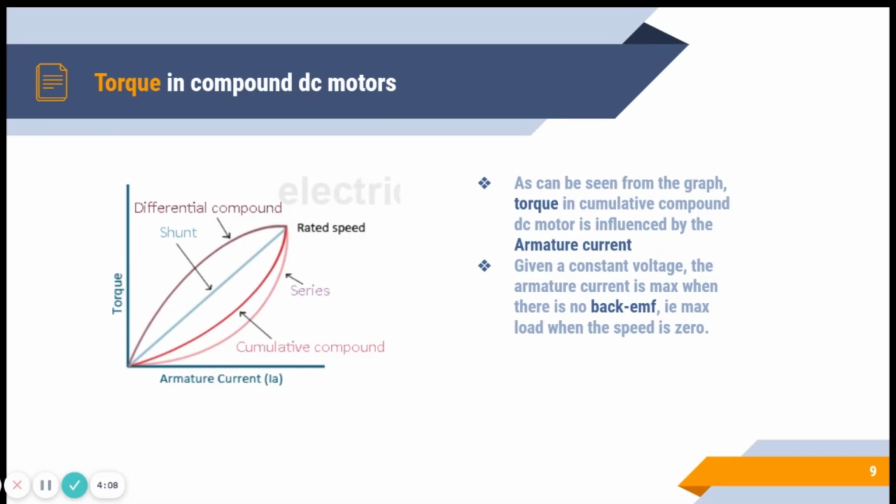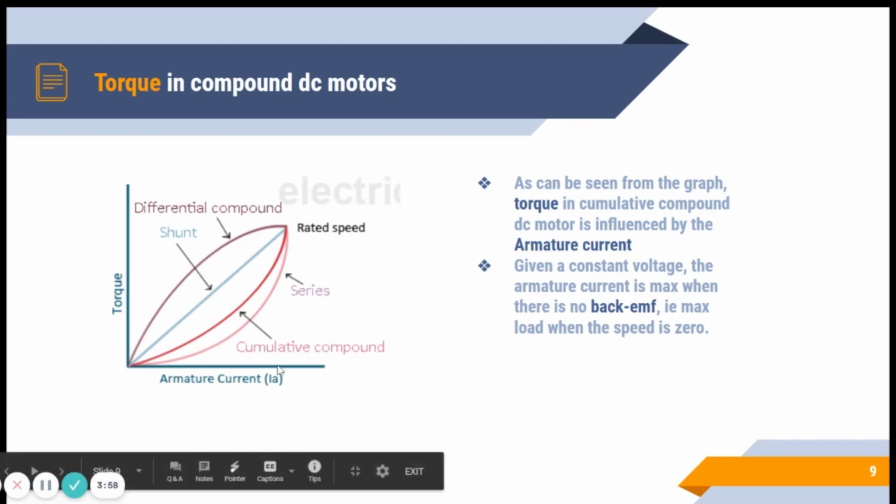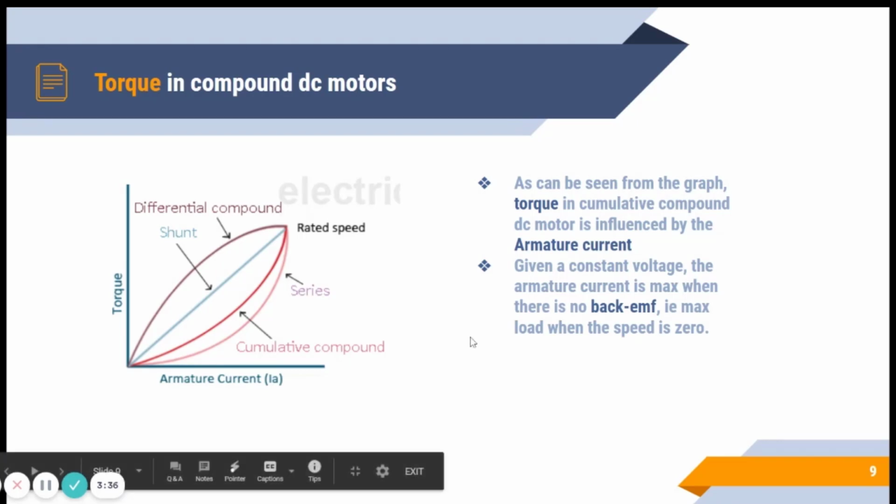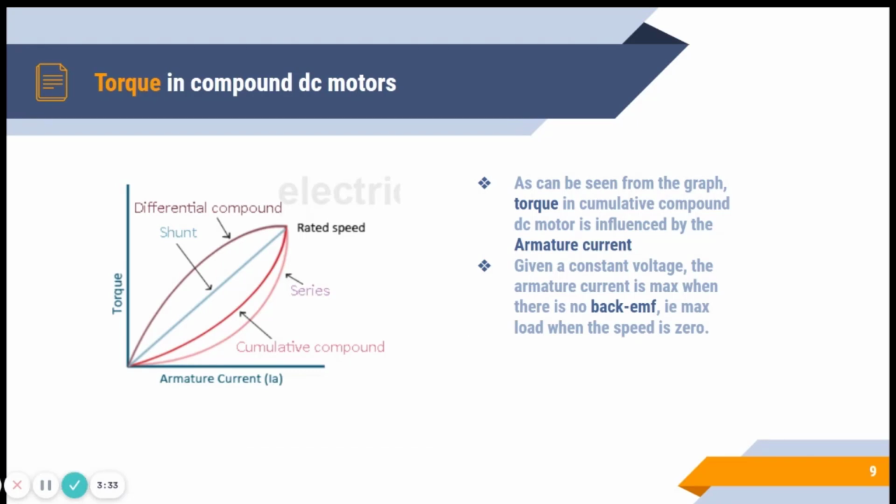We can control the speed of the motor by varying the voltage, but controlling the torque is not as straightforward because the torque depends on the current, the current depends on the back EMF, and back EMF depends on the speed. So if we apply a constant voltage to a motor, let's say 12 volts DC, then it will have a constant speed, the no load speed, the maximum speed of the motor. And then the more you add load, the more it slows down. When it slows down, it draws more current, which means it's generating more torque according to this graph.